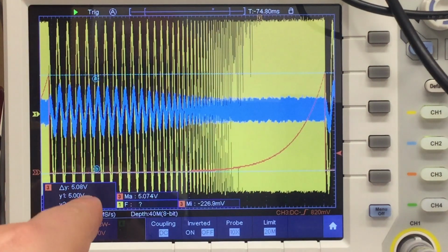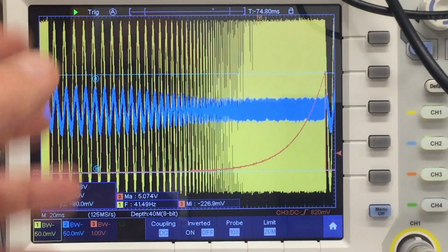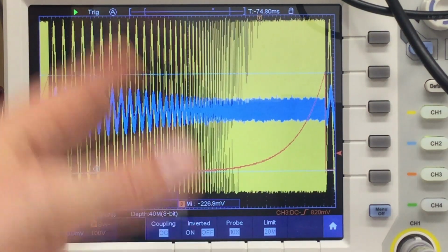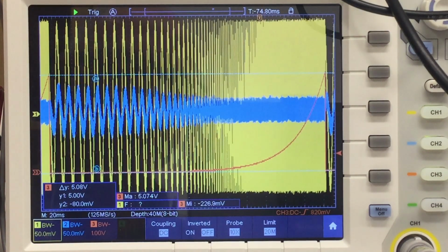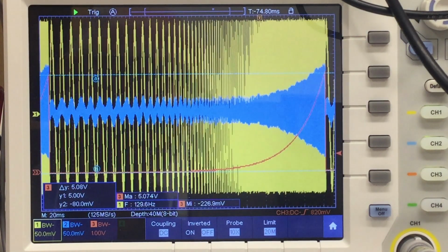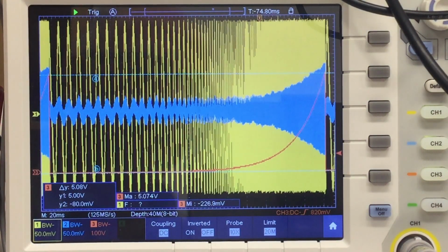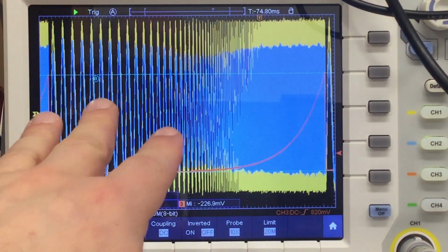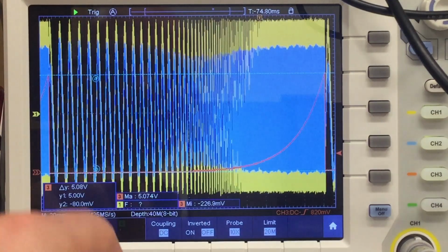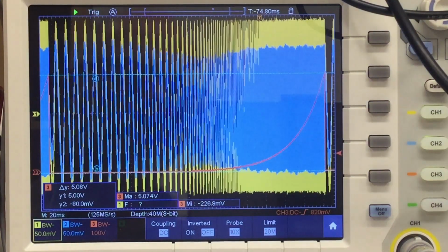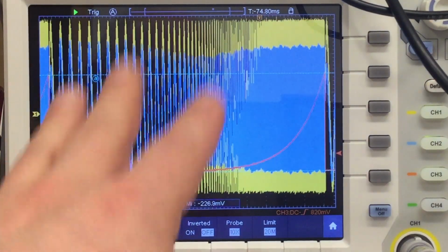The next setting also looks like a low pass. Oh, maybe the odd electrolytic capacitor dried out here. But the high pass is working perfectly. No filter at all, you immediately recognize that because the amplitude goes up. These will be only very, very cheap RC filters in that box.